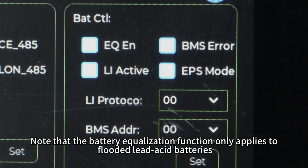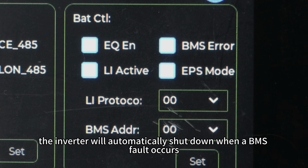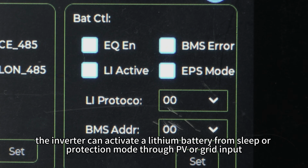Note that the BMS equalization function only applies to flooded lead-acid batteries. If the BMS fault switch is turned on, the inverter will automatically shut down when a BMS fault occurs. When the lithium activation switch is enabled, the inverter can activate the lithium battery from the sleep or protection mode through PV or grid input.